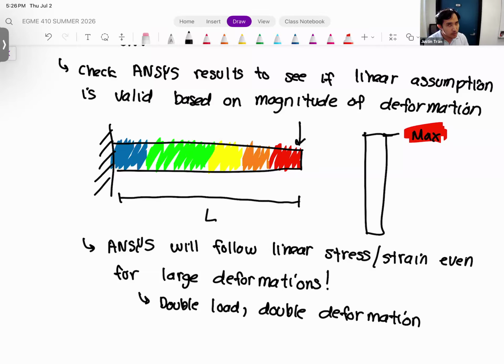Okay. So you saw this a little bit yesterday as well. When we tried to do the default mesh in ANSYS without applying any settings for the sizing or the method, we were able to get a mesh, but the mesh that we got, I would never say is appropriate to run a practical, reliable simulation. Okay. So the choice of material model is the same. ANSYS is always going to pick the simplest way to give you a result, but you have to be the judge to see whether the result that you're getting is actually reliable and accurate.